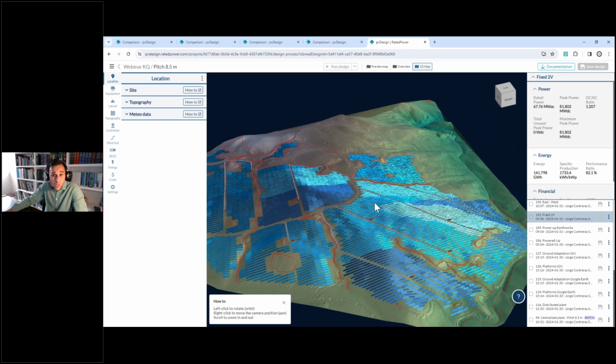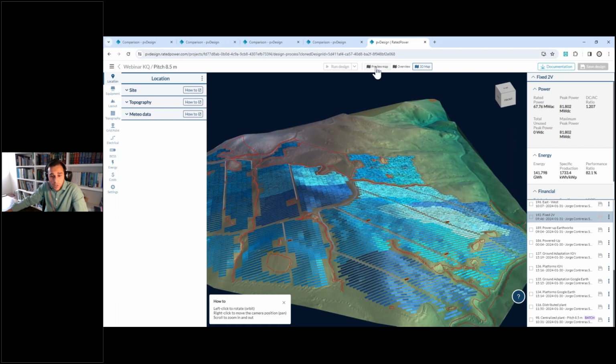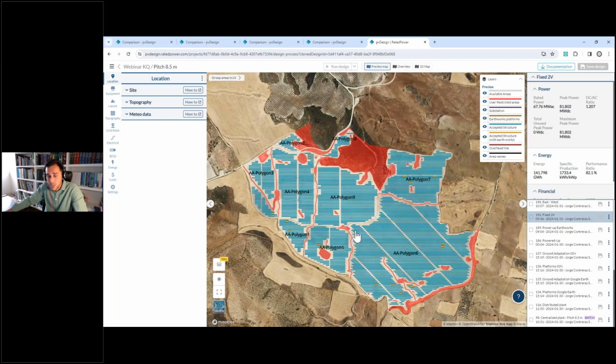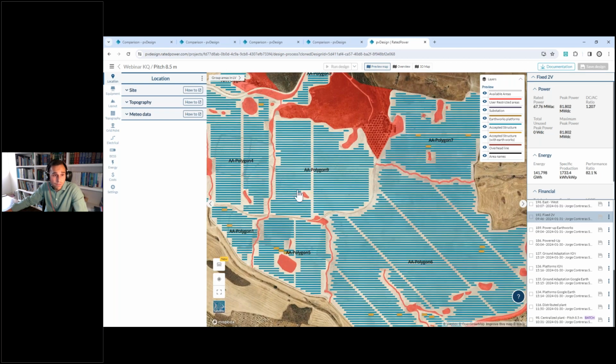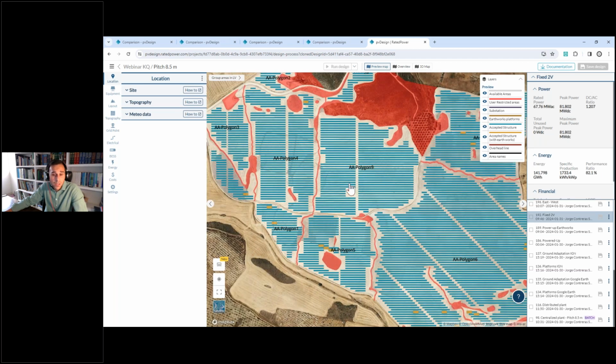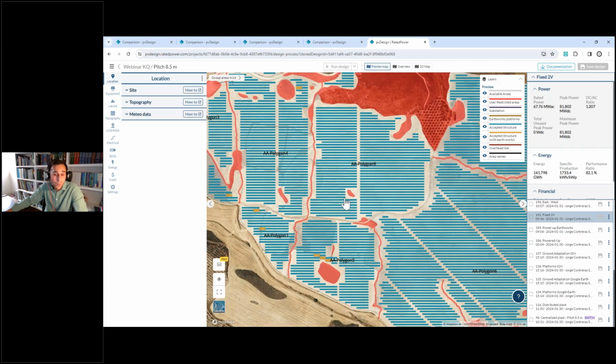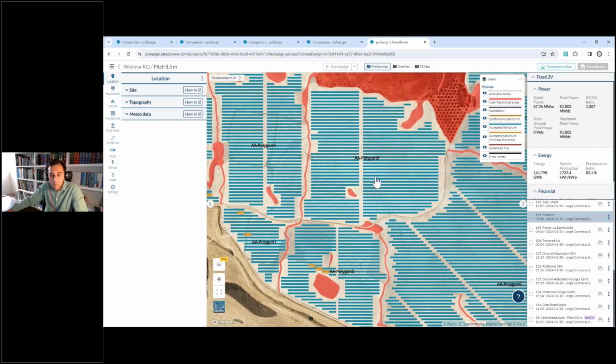But still, as we have done a PV plant with multiple parcels, we could reach an agreement and say, okay, the optimal pitch distance for the fixed structure could be at least similar to the one used in the trackers, considering that most of the slopes are south facing, so we could decrease the distance between rows.